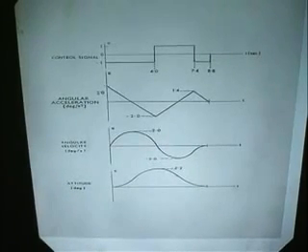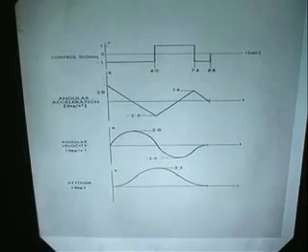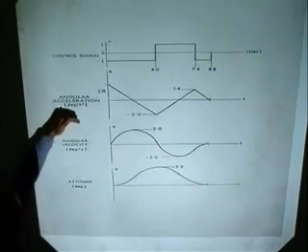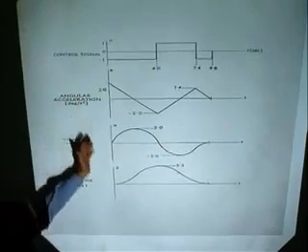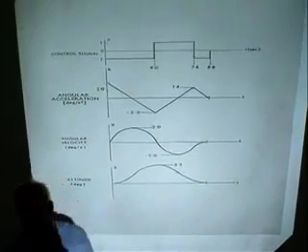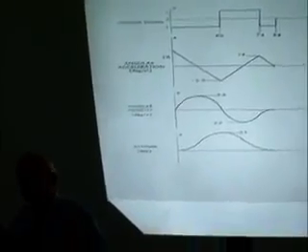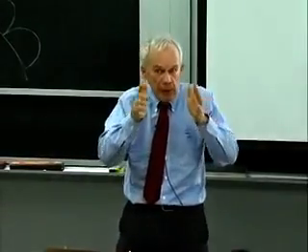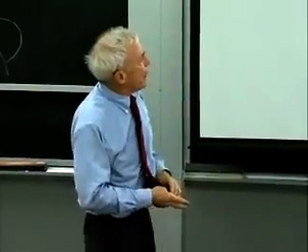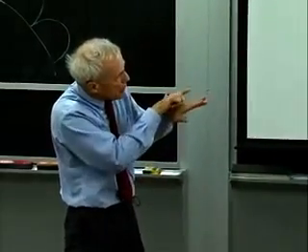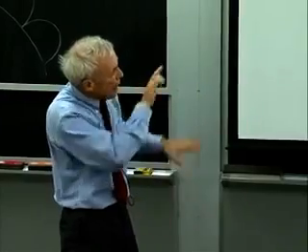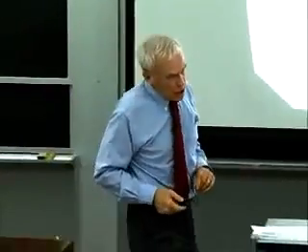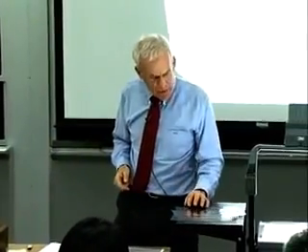And for some of the numbers that we worked, the various levels of control effectiveness or so on, if this was the level of the initial misalignment, it was going to take something like 9 seconds to capture that initial state error and slowly bring the spacecraft back to right on 0 attitude error, 0 rate error, and 0 bias torque. So that was going to be the nature of the solution according to the theory. And so we programmed it up for